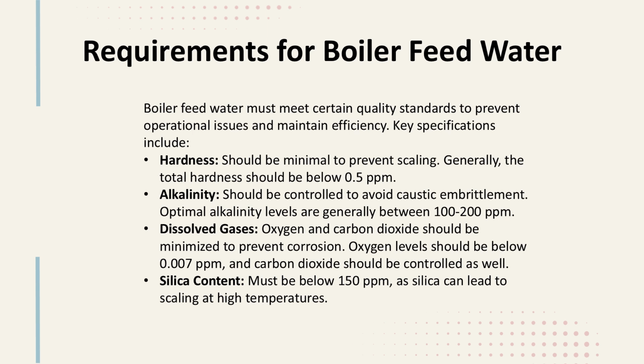Dissolved gases. Both oxygen and carbon dioxide must be minimized to avoid corrosion. Oxygen levels should be below 0.007 ppm to prevent oxidation, and carbon dioxide should also be controlled to avoid carbonic acid formation.